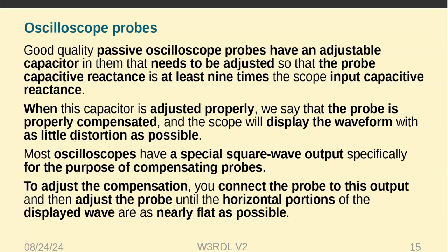They will have a special probe, and it won't work if you don't have it grounded. You'll generate a square wave, and you adjust the probe to try to get a perfectly square, flat top on the square wave.